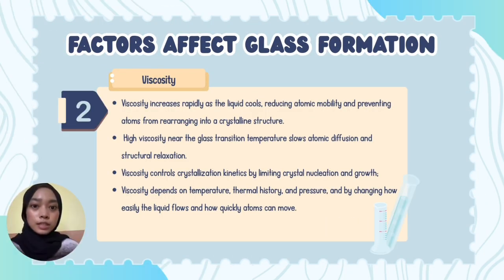Next is viscosity. Viscosity increases rapidly as liquid cools, reducing atomic mobility and preventing atoms from rearranging into crystalline structure. High viscosity near the glass transition temperature slows atomic diffusion and structural relaxation. Viscosity controls crystallization kinetics by limiting crystal nucleation and growth.